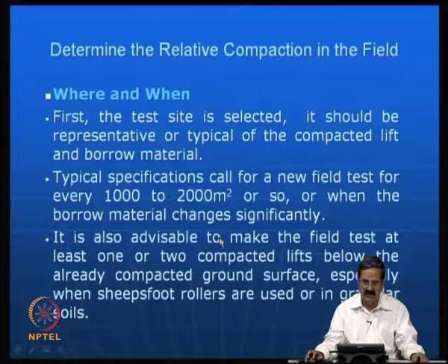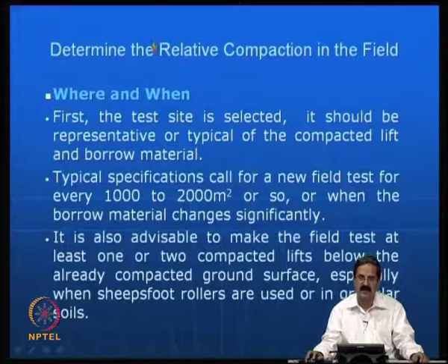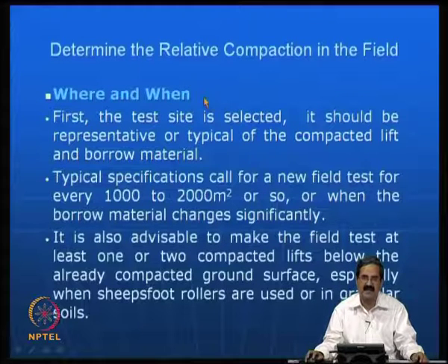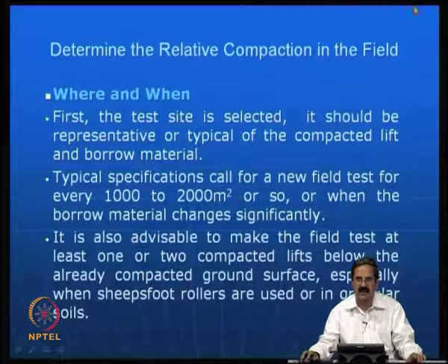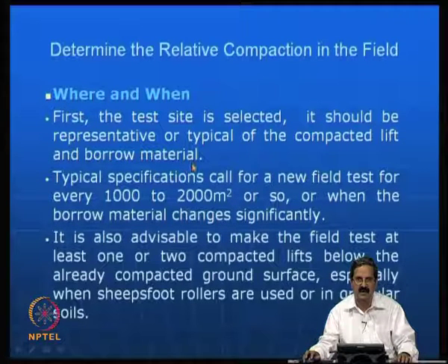So, how do you do this in the field? This is very important. First the site is selected, and once you select the site, it should be representative of the typical compacted lift, because you are trying to take a 30 centimeter lift and all that. It should be of that material and also the same borrow pit material that you have selected.